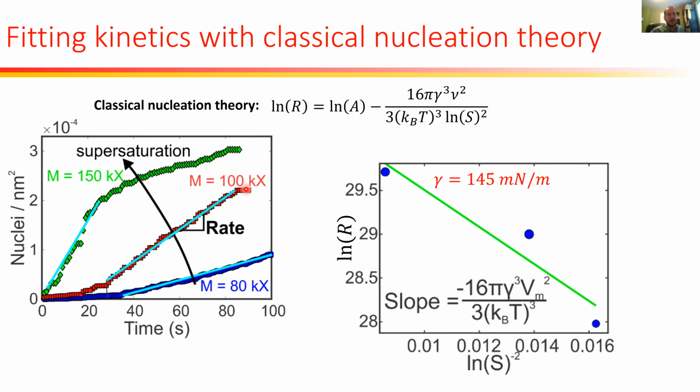At the beginning, the only option the metal atoms really have is to nucleate at the interface. And then once the supersaturation ratio gets small enough and we fill up enough nucleation sites, it's easier for a metal atom to just attach to an existing nanocrystal. So it completes right here. And we can see for the green one, it completes up here. You can see the slope changes, which we're not sure why that happens yet.